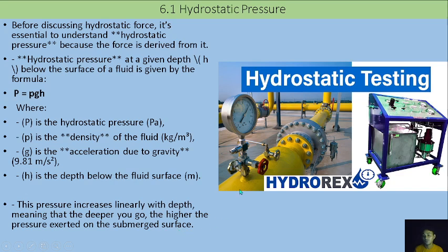on the submerged surface. On our pipelines, we also have hydrostatic testing. It is a test to ensure that there will be no leakages on our pipelines during usage. Hydrostatic testing is just like putting water in it, or putting air or any fluid inside, and then you close all the valves and wait until a specific time that there will be no pressure loss. If there is pressure loss, it means that there is a leakage on your pipeline.